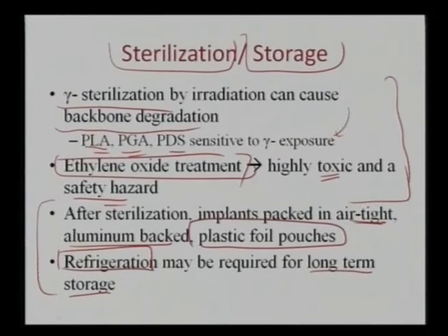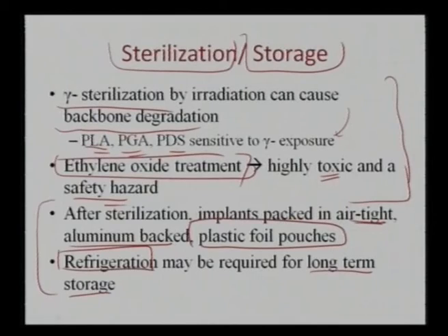So we can see there are certain aspects which are related to either the processing or the sterilization. That's how we can control the overall degradation and be able to process it successfully, sterilize it, as well as store it for certain time, so that it can be used successfully in patients. So that's what we saw in this lecture, that we have degradable polymers for which the erosion or the bioerosion can be controlled,